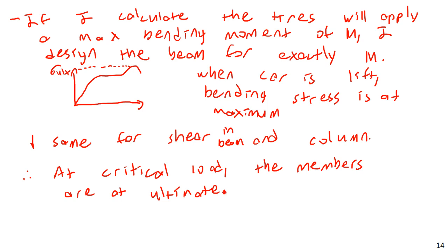And so, again, this is still engineering. It's not very good engineering, but it's still engineering. I'm not just choosing a size of a beam out of the air. I'm looking at it and saying, okay, what is the heaviest thing I ever expect this to lift? What is the heaviest truck the mechanic has ever had to lift up? And then designing everything at the limit.